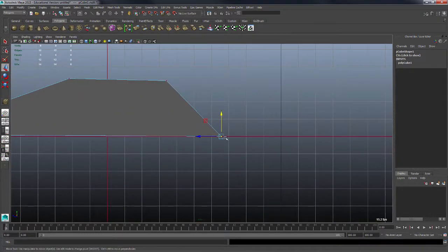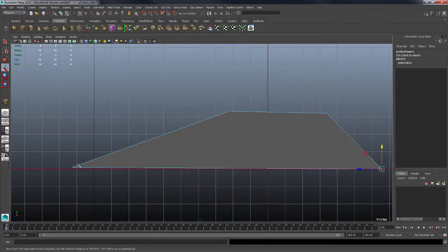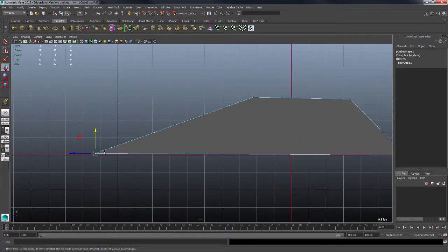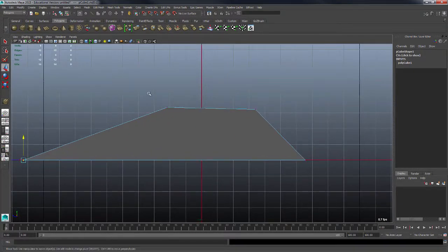And you can see how I've snapped down to that, just holding down X. I'm snapping down here, and I can grab these verts here, hold down X, and then snap those down. And if I wanted this to be flush with this line up here, I could hold down X, and then hit snapping on that.